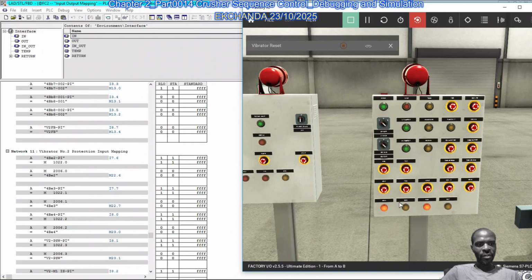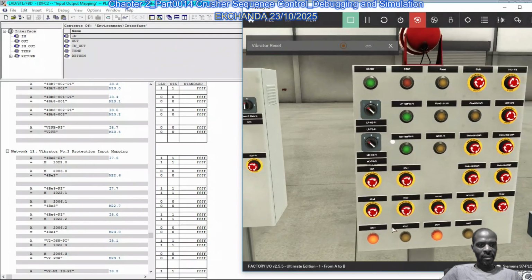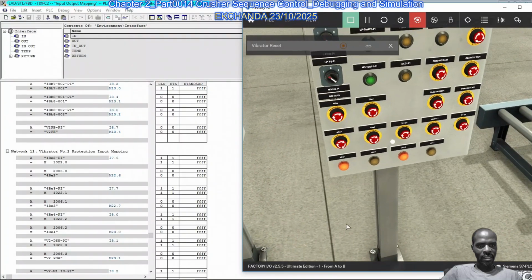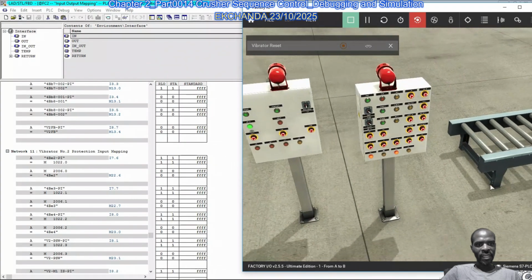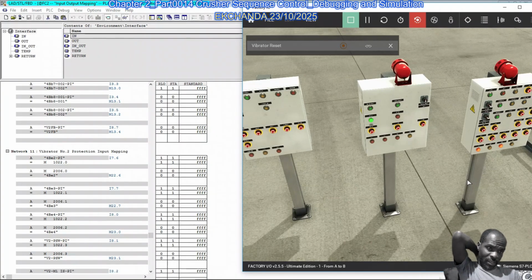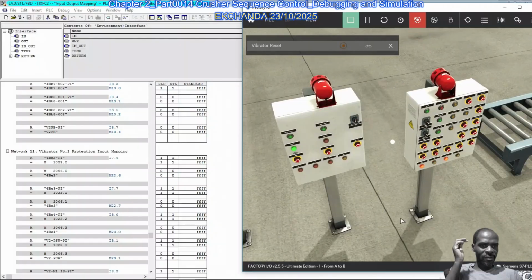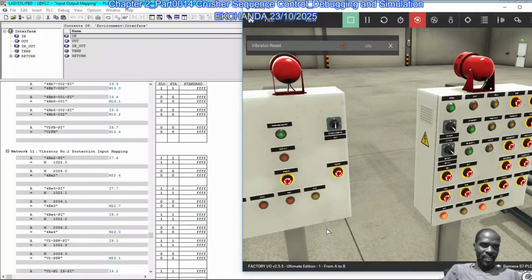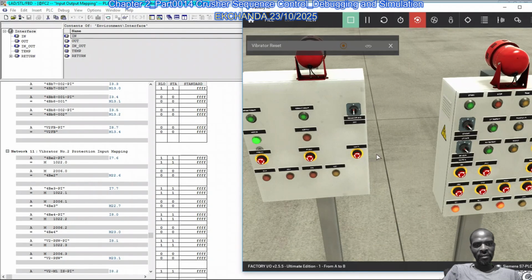And then of course the lubrication system is running. Okay, don't know if you can clearly see that. The lubrication system is running, the crusher is also running, irrespective of the operational state of the vibrators. Okay, but the only issue I have, I just thought of this later, is that the hydroset is never supposed to run when the crusher is running, but the way it is.